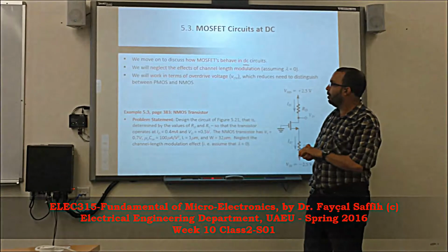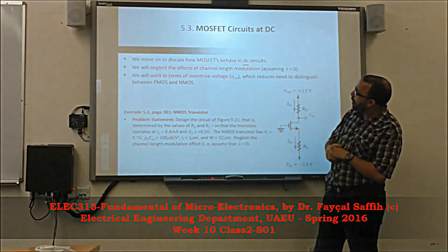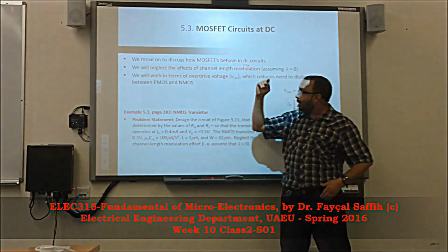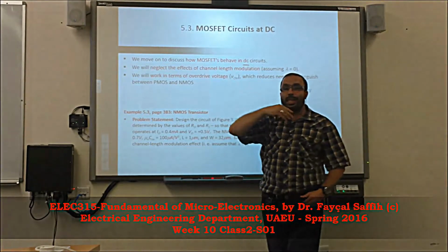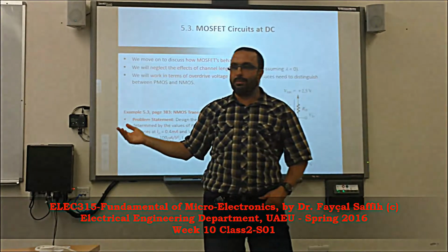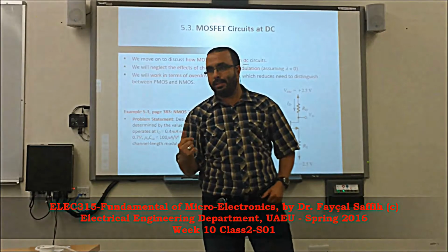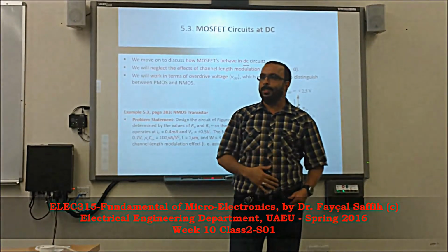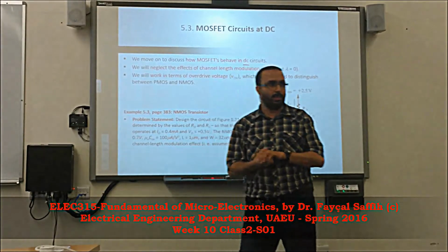We are not doing that. Alright, and so far also, at some point we neglected the channel length modulation. When we neglect that, that means we neglected R0. And typically, numerically, R0 is a very high resistance. Make no mistake. It's very high. But now we can know how high it is. That's all. Okay?